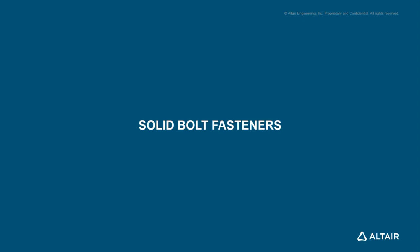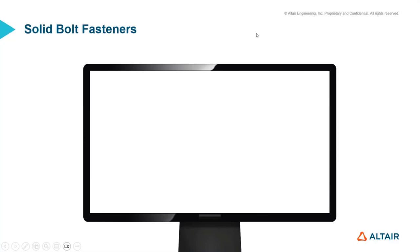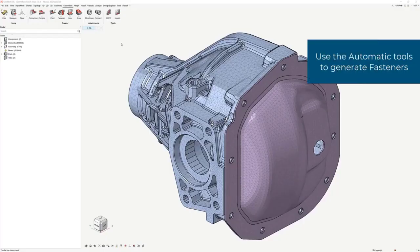And the last one I'm going to cover today is the solid bolt fasteners. So this is something that we have been requested for a very, very long time, and I'm very excited to finally be able to present this one. Solid bolt fasteners is one of the biggest use cases we keep getting asked for. So what we have here is the ability in HyperMesh via connectors to create solid bolts alongside with the pretension and the contact, all automatically created for you.